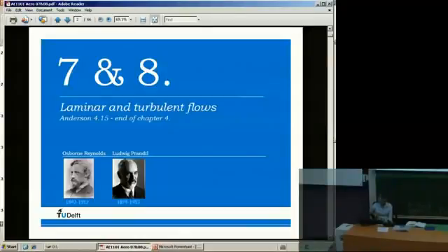Okay. So far all the relations we derived are valid for inviscid flows, right? We assumed isentropic flow, so reversible flow, so no friction or dissipative effects. With Bernoulli, we derived it from a pressure force balance over a fluid element, and there we also neglected viscous effects. So now a small lecture on what happens inside viscous flows.